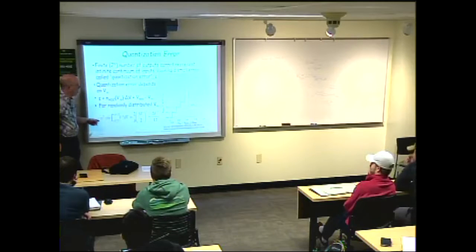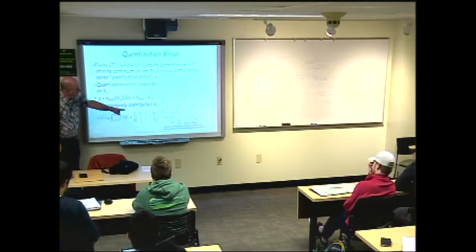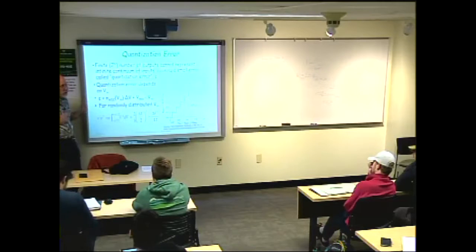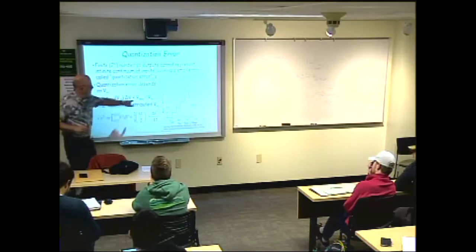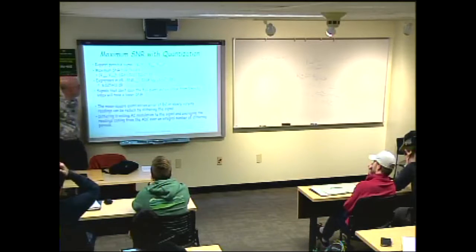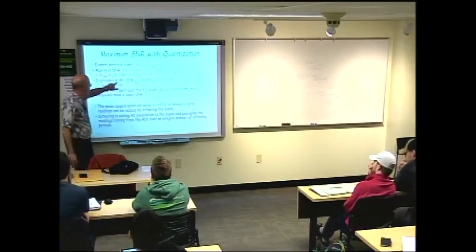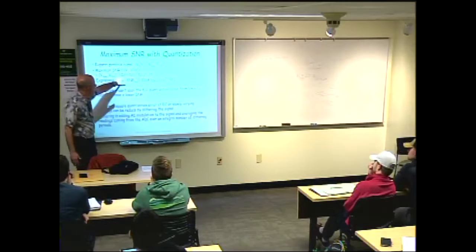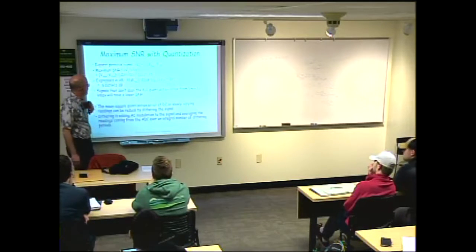I think what I have to do is divide that formula by the full range of the A to D in order to get it to come out right. So I think that's probably what's going on, which would imply that in this formula we would actually have another factor of this dividing this up in the numerator.